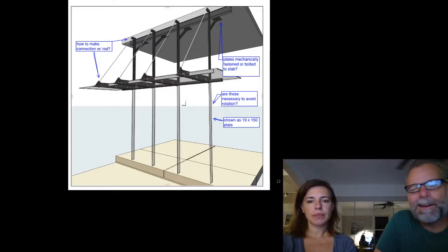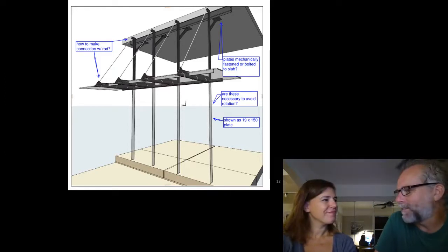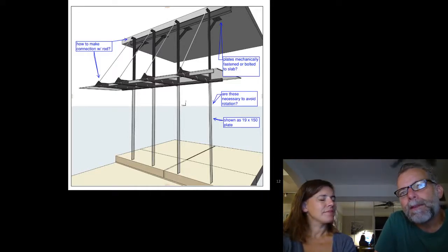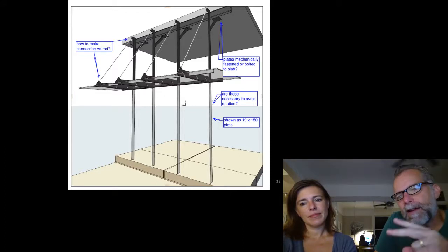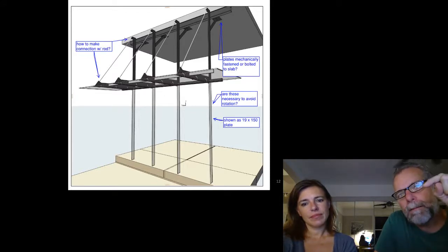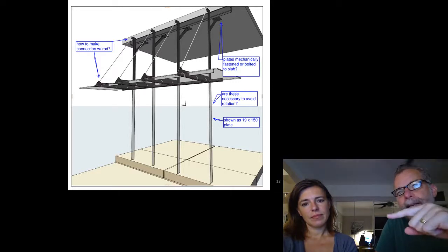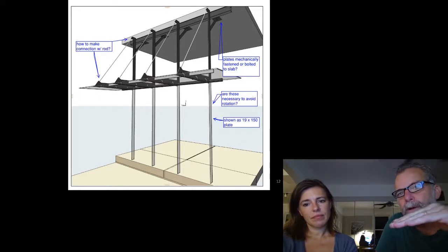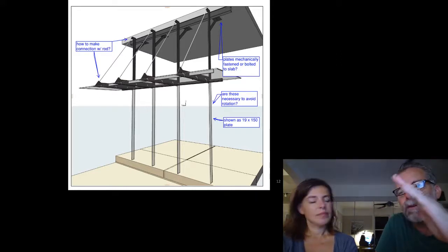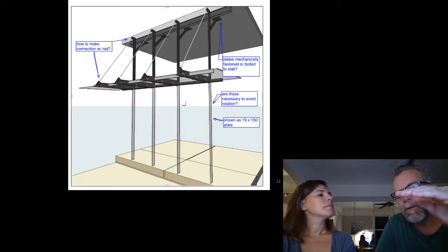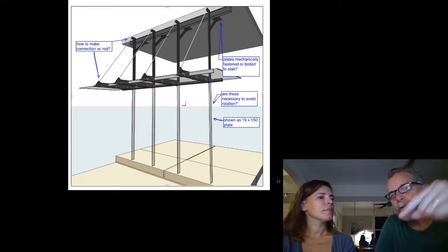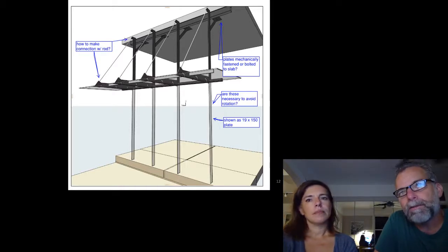That's right. It's a particularly unsatisfying solution when we have to tell an architect they have to use a pipe instead of a rod. The other alternative we have is to have two different load paths. For uplift, we could make the canopy a cantilever. Because the uplift force is going to be quite a bit smaller, we cantilever the canopy out of the wall for uplift. And then in downward, we're still moment connected at the wall, but in downward loads, we have the additional support from the tension rod.